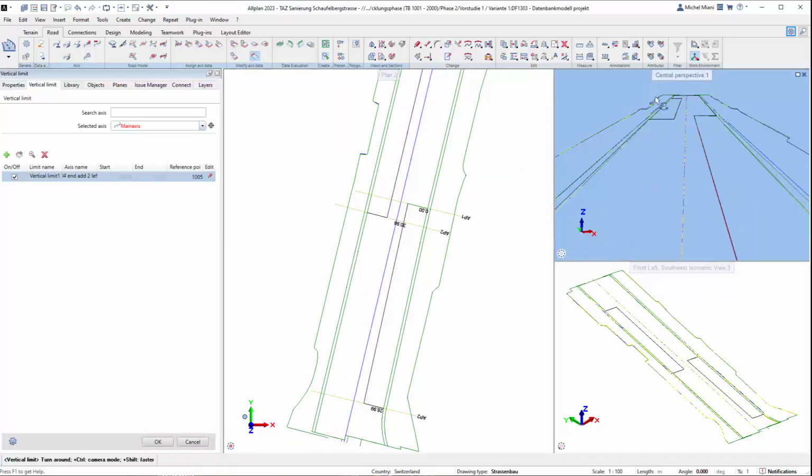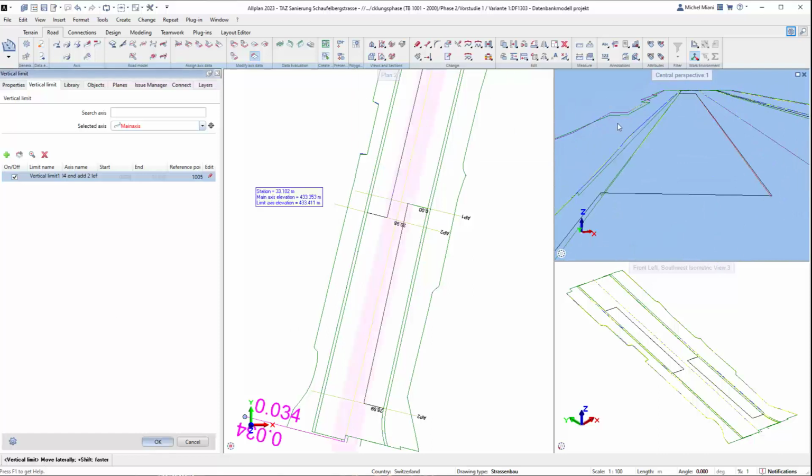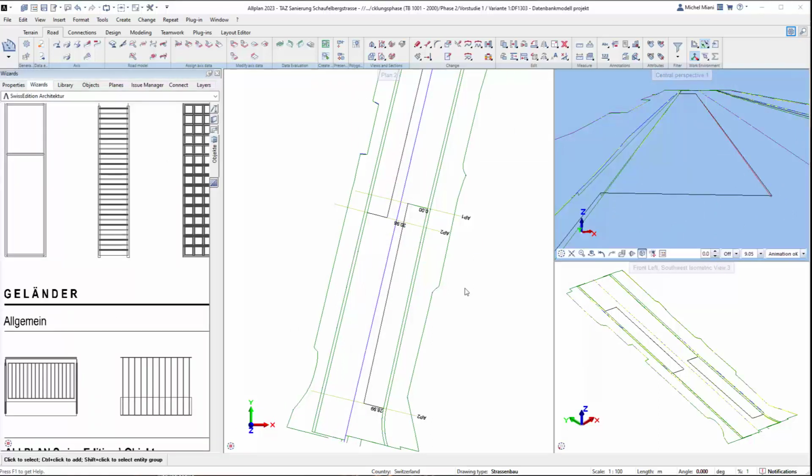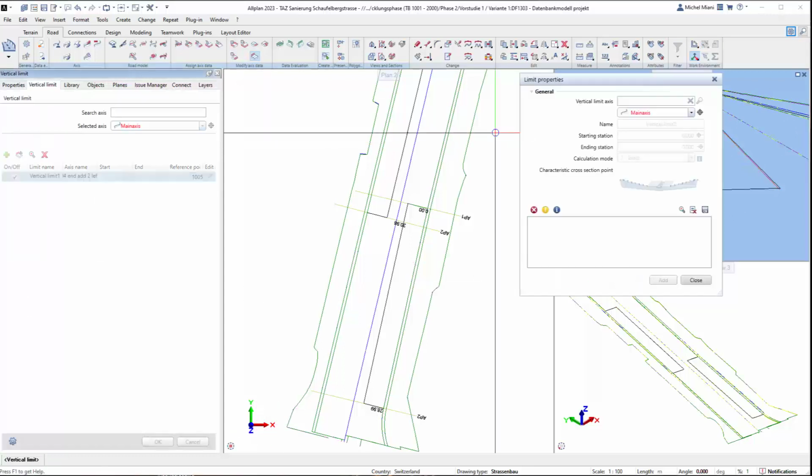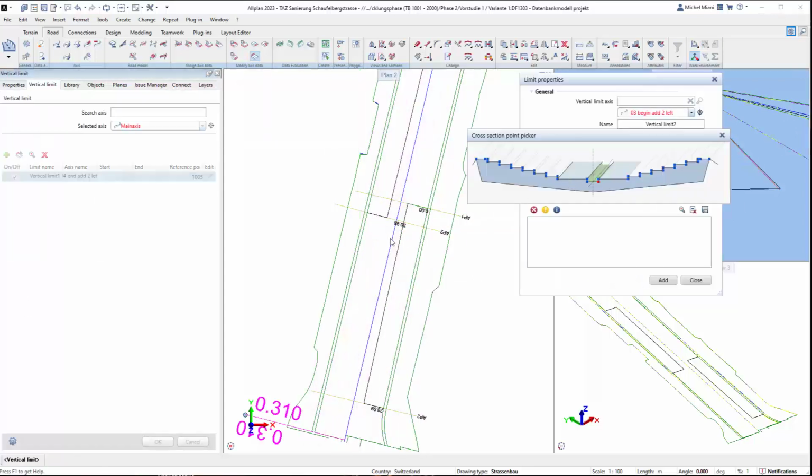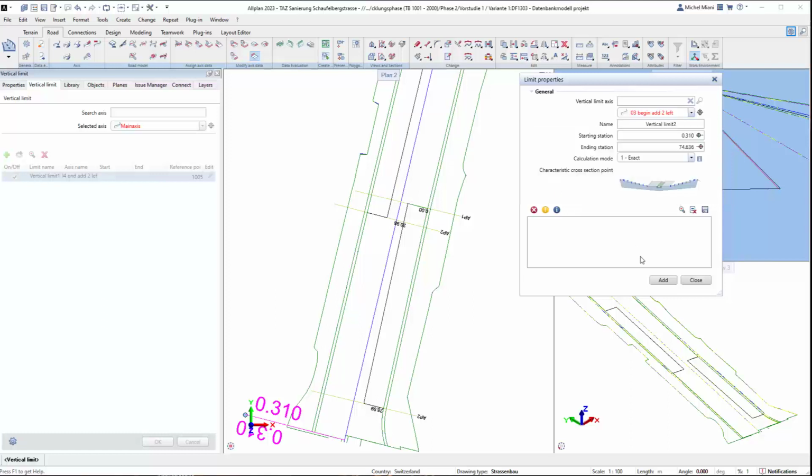If there is no 3D polyline, you can create the height using the vertical geometry. You create a composite element or a 3D polyline, and with a vertical geometry you can create the height position.